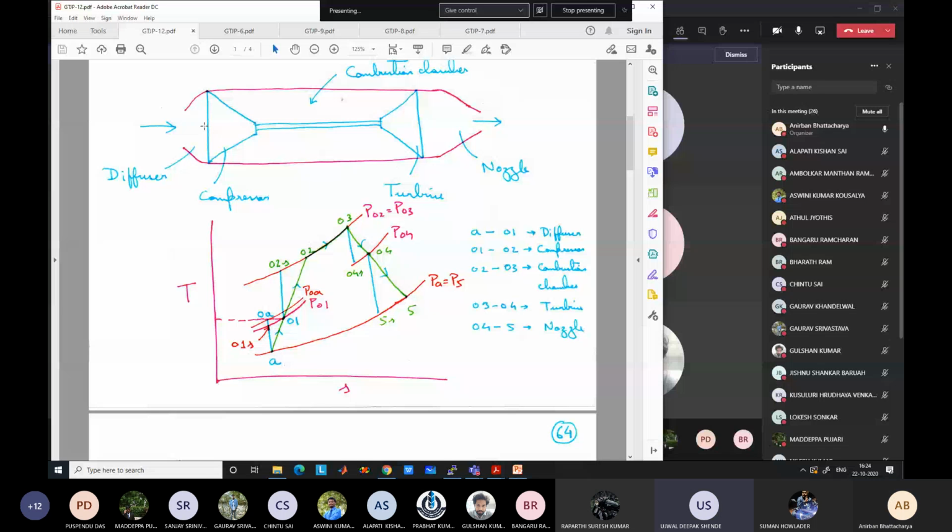It will be same, right? Because stagnation enthalpy is same. Correct. Same. So you don't hesitate. Tell me that it will be same, because there is no change. Stagnation enthalpy same means stagnation temperature also same, because enthalpy and temperature are just related by H equals CpT. Whether it is static or stagnation does not matter. So because stagnation enthalpy is same, stagnation temperature will also remain same in the ideal case.